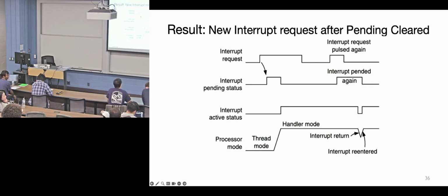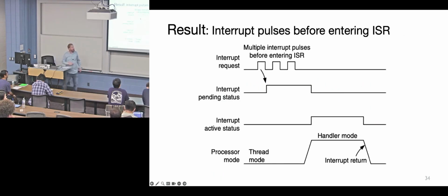So in the previous one, what did I do wrong over there? It's similar. We couldn't have three. But 3 pulses happened before you were in it, right? So these 3 pulses occurred before you got into your interrupt active state. So we've lost that edge information. But I suppose if that pulse happened here, then the pending would get asserted because the interrupt went high. Then when you came out of this, you would go, okay, I have to go back into it.